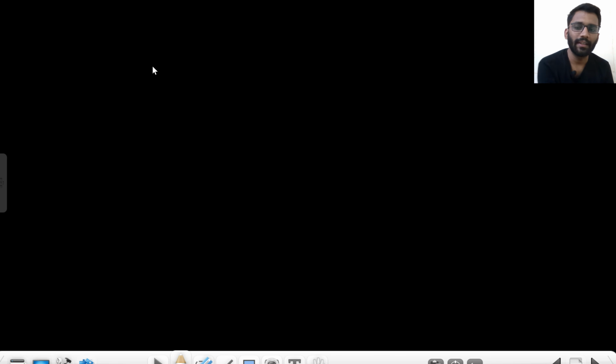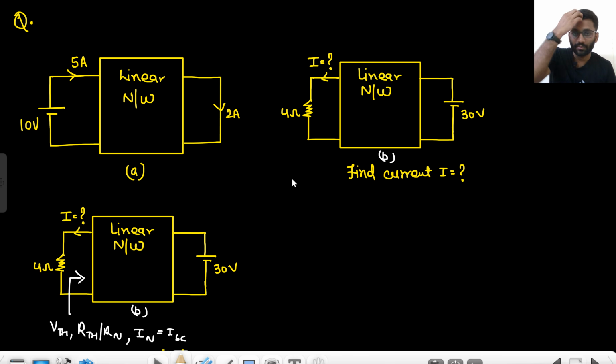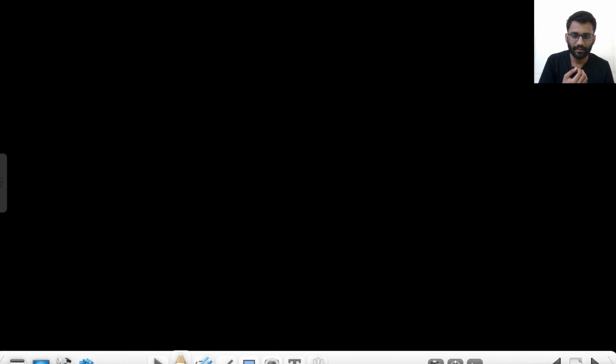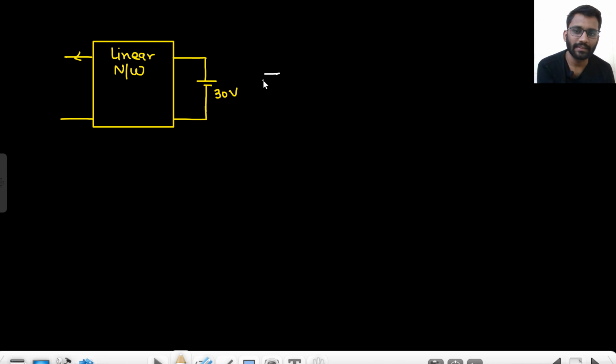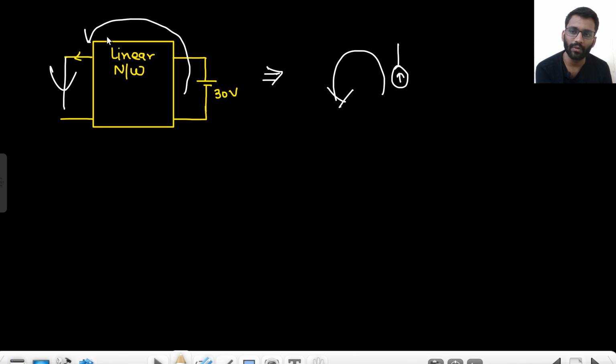Okay. So basically, now let's just take this circuit. I will just copy this circuit there. Now this circuit can be replaced with a simple current source. What will be the direction of the current source? Upward. Why so? Because here the current direction was this, so it has to be like this so that the current flows in this direction, since we are replacing it at this side. So it has to be upward, right? So that's why it is upward.